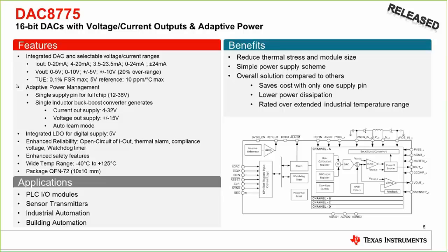voltage output. But if we're talking about something with the DC-DC active, and again, in the case of plus minus 24 milliamps, it's closer to 2 milliseconds to slew from negative full scale to positive full scale. Full tracking doesn't apply for the voltage output, so it would always be 1 microsecond.